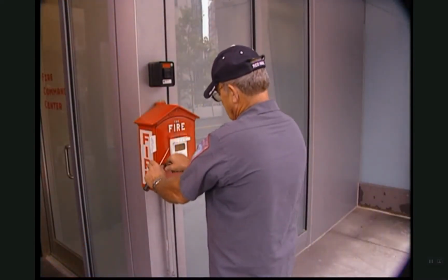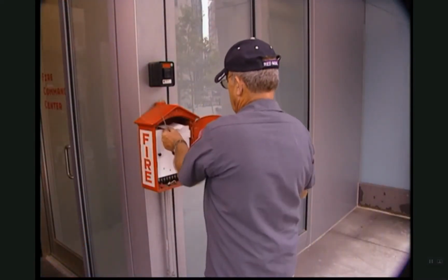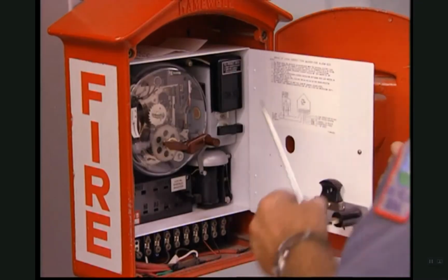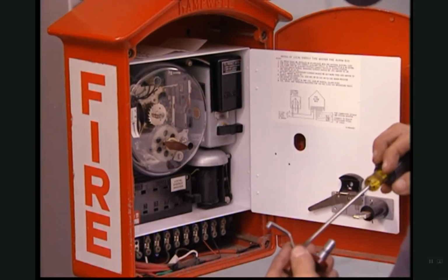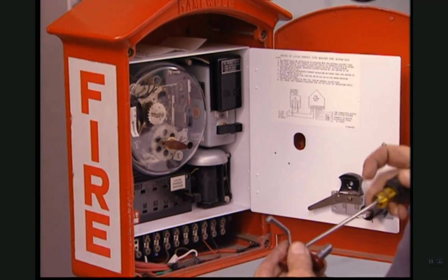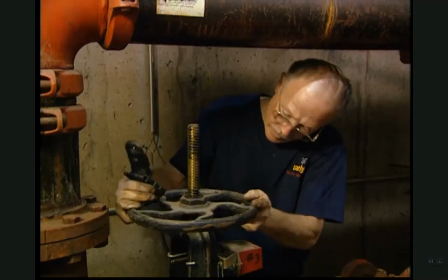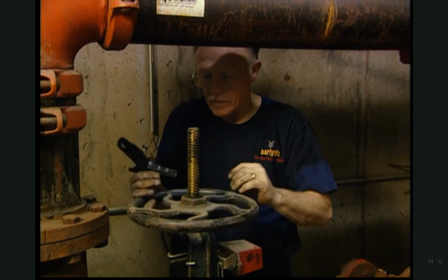Some fire alarm systems transmit signals over municipal circuits, interfacing with these circuits at a master box. The master box may double as a manual pull box for the general public. Water flow devices are to be tested semi-annually.